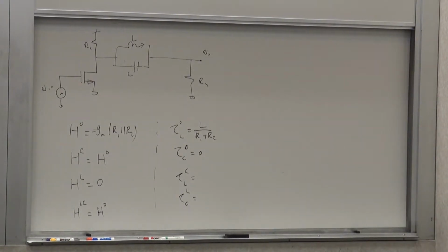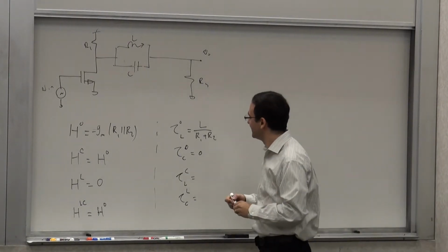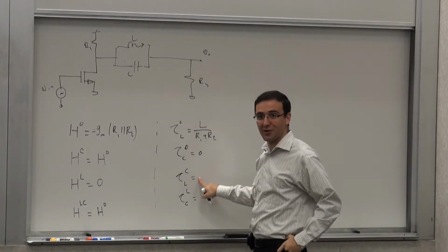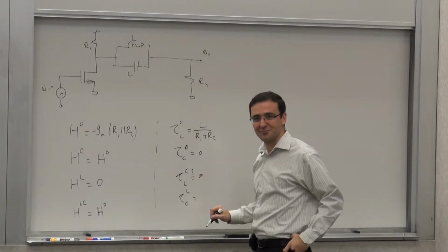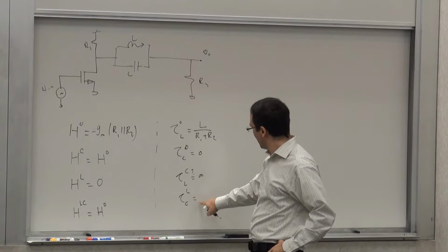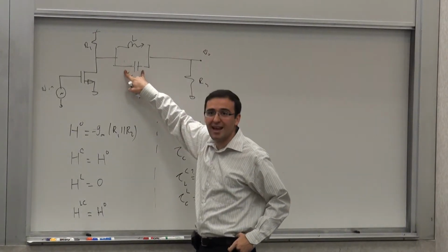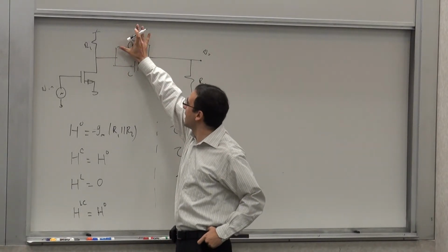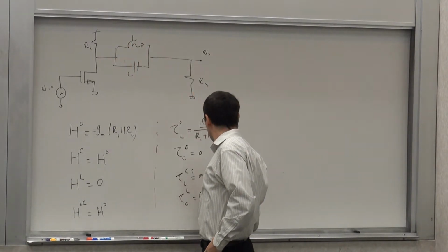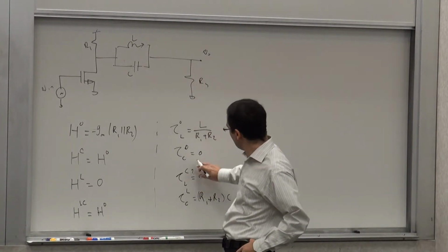Which one will you calculate? Tau CL. Why? Okay, alright, exactly. So what you know already what this one is, right? You're thinking this is infinity, but we'll check that out later. Tau CL. What's the resistance seen by C when L is infinite valued? So this is not there. Again, R1 plus R2. And is this infinity really?